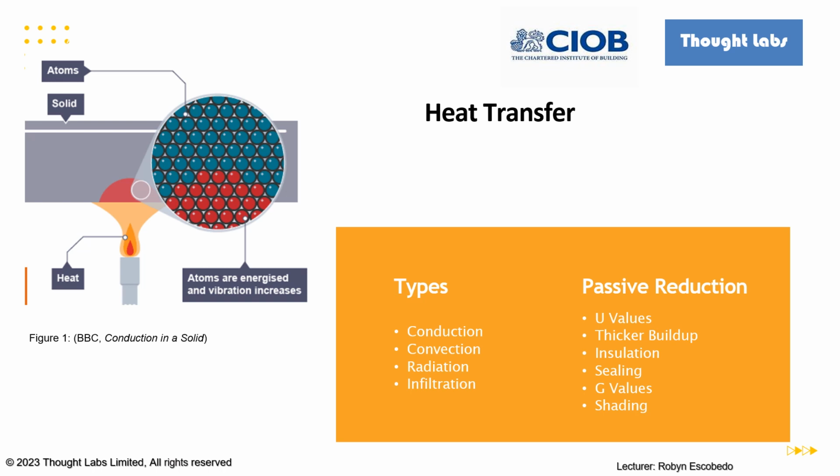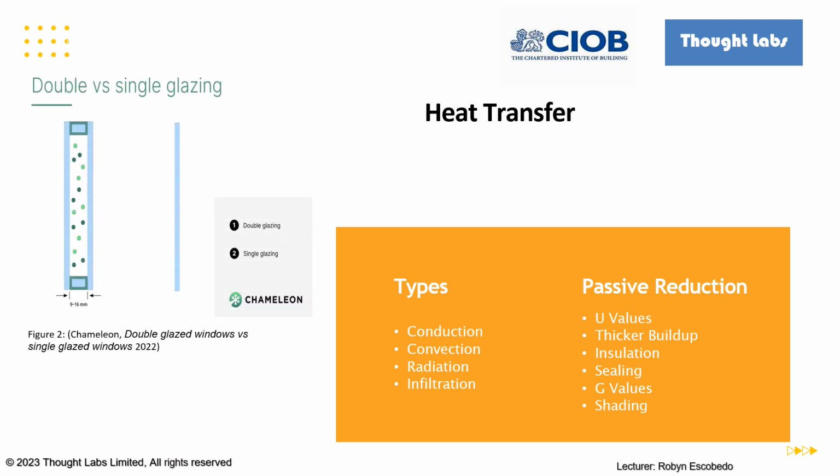If you consider this in a building scenario, one side of a window may be heated, whereas the other side, especially on a winter's day, may be cold. Conduction would occur through both the window and the window frame. The heating system in a building will need to account for this heat loss in order to overcome it and ensure a comfortable ambient temperature for the occupants.